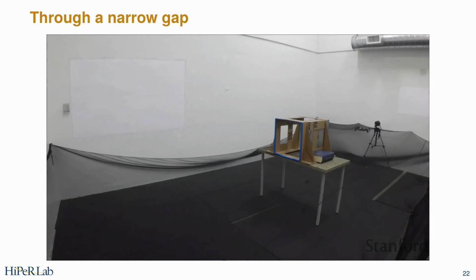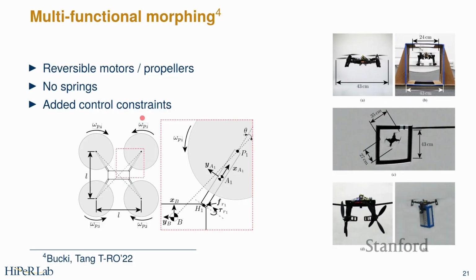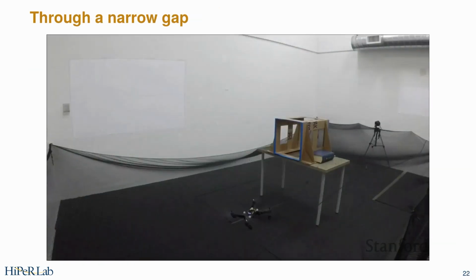And then transition back. Maybe jump back, apologies. The way that the hinges fold is not quite aligned, and this is so that you still have yaw authority, which gives us the ability to hover the system in this reverse configuration. It is horrendously inefficient in the folded configuration; you wouldn't want to do this for a long time.